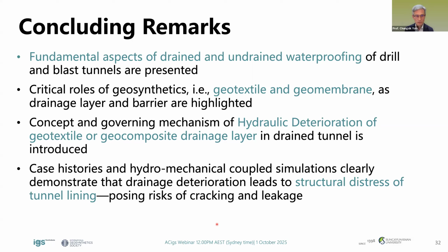And a practical approach is discussed in this presentation. I believe the practical approach that I proposed can reduce the risk of clogging potential when we use geosynthetic as a drainage layer in a drained tunnel of conventional tunneling.